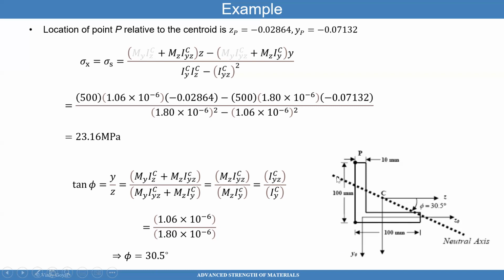And what that means is that on the neutral axis, the stress there is 0. The farthest point away from the neutral axis will give you the highest stress. I have the feeling that maybe it's this point right here, but you may want to check. But you're looking at the distance farthest away from the neutral axis, which is where you'll get the highest stress. That concludes this particular lecture.